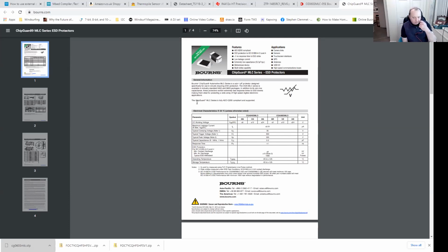But now they blur the line a little bit because after 74, which means TTL logic level, there'll be a collection of letters about whether it's low power, whether they are Schottky diodes, or whether it's actually a CMOS circuit with TTL logic levels in it. So it does start to get a little bit blurry.